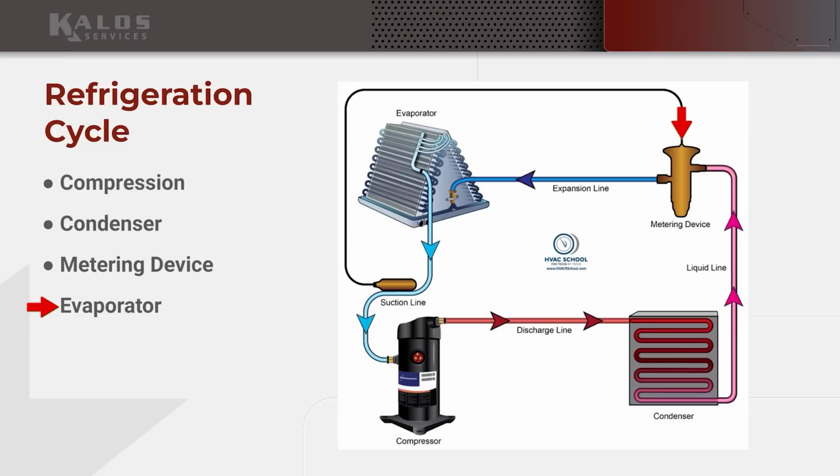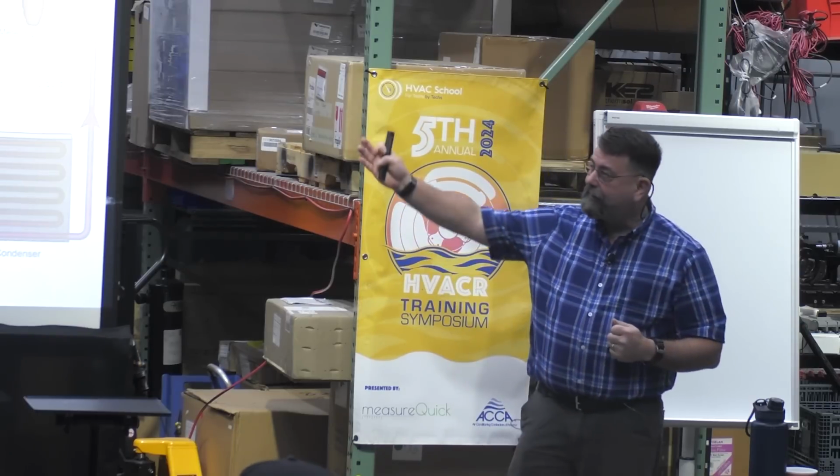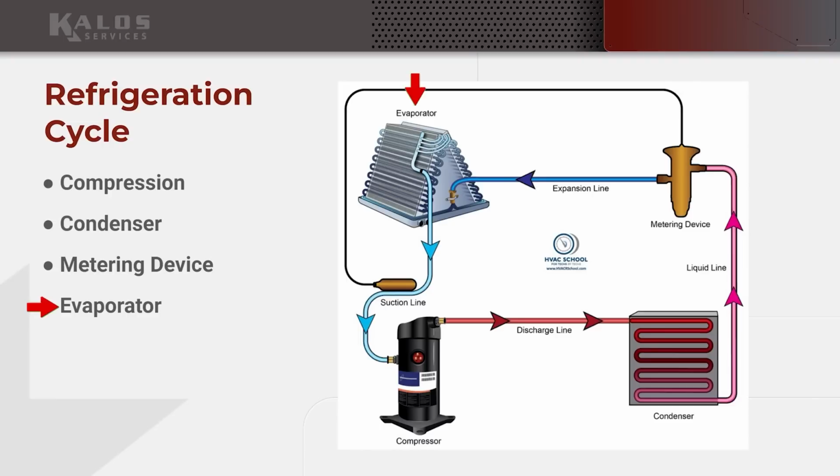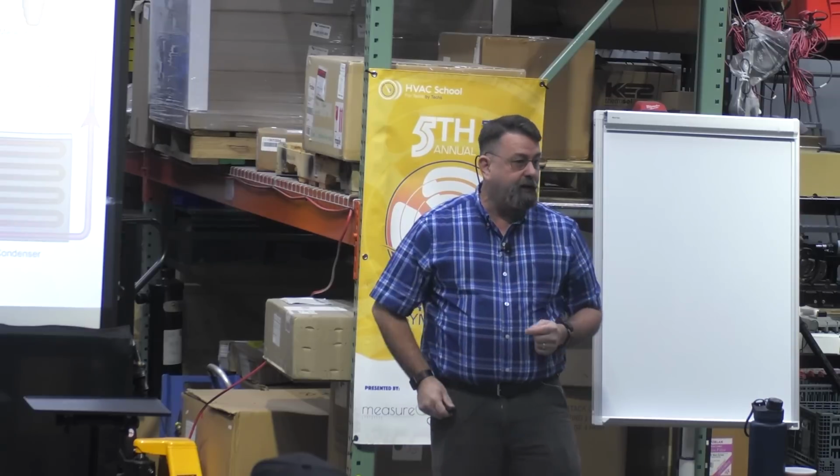We're going to absorb that heat, and it's going to cause my refrigerant to change states. I'm going to have that latent heat exchange exactly the same, and that's going to absorb all that heat into that refrigerant, and it's going to come out as a dry superheated vapor, right? Yeah, we're going to do that too, and we're going to send it back to our compressor, okay? So I'm going to take you through what that looks like, all right, on our side.